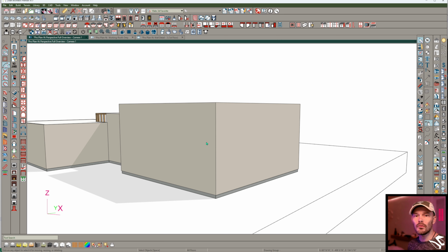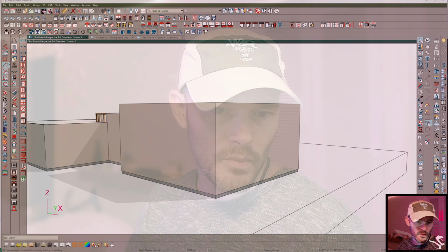That means I don't necessarily even need to know what the fascia height is compared to the terrain, or what the ridge height is inside of a vaulted ceiling, which is something that's measurable when I go to an existing home. When I walk into a home, and let me just switch to my camera, in my jurisdiction, in my area, we've only got about 4 or 5 counties. In those 4 or 5 counties, we only have about 4 different roof pitches. We also only have about 3 different plate heights. We're going 8 foot, 9 foot, 10 foot plate heights at 4 and 12 pitch, 5 and 12 pitch, 6 and 12 pitch, 8 and 12 pitch.